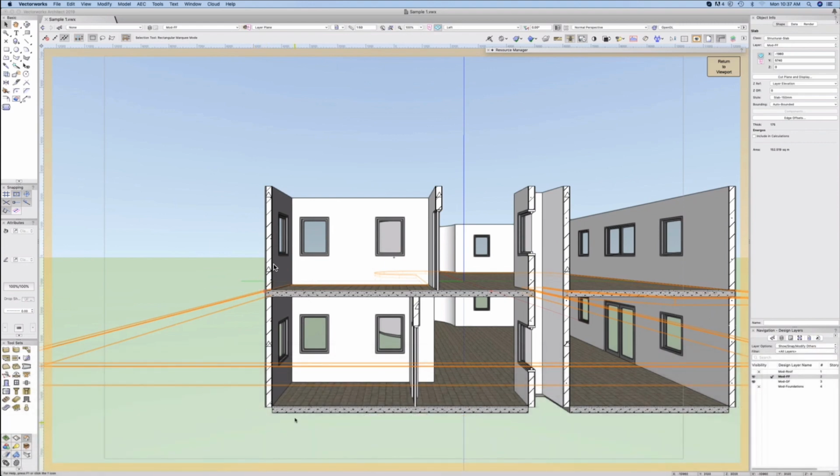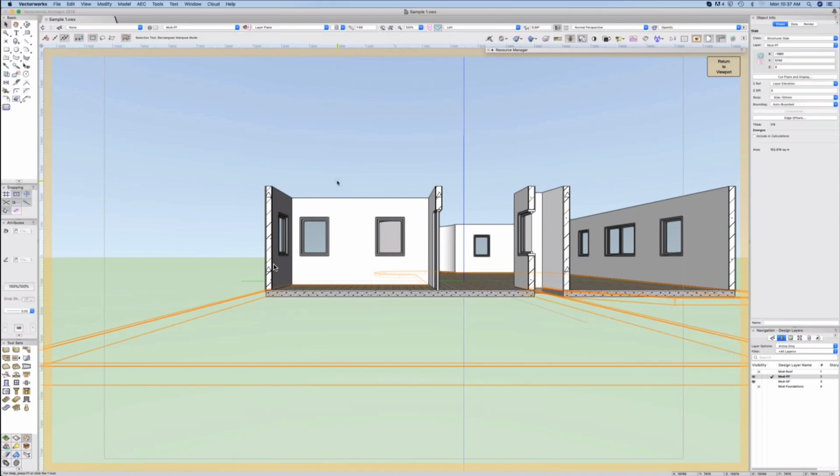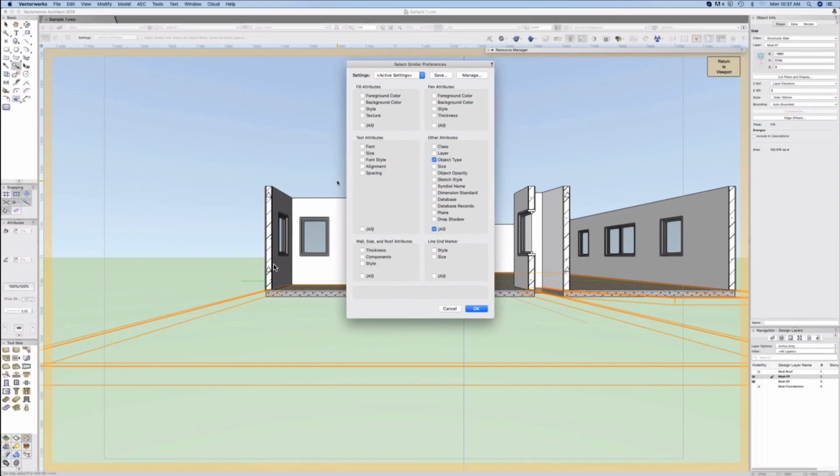The first thing you need to do is put it into a mode where if you use your wand tool, it won't select all the walls, just the first floor external walls. Okay, so a good one for that is Command Alt 5 potentially, or Command Alt 3, one of those two. Try Command Alt 3. There we go, so that was that active only thing. Now double click W. Okay, so this is our wand tool.